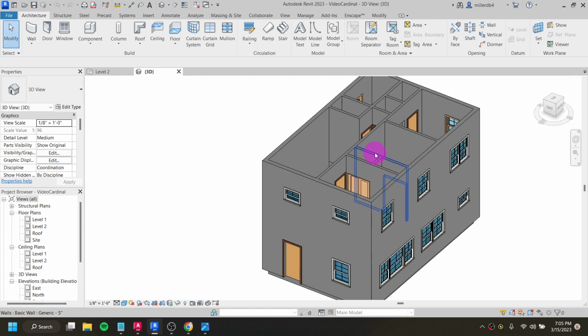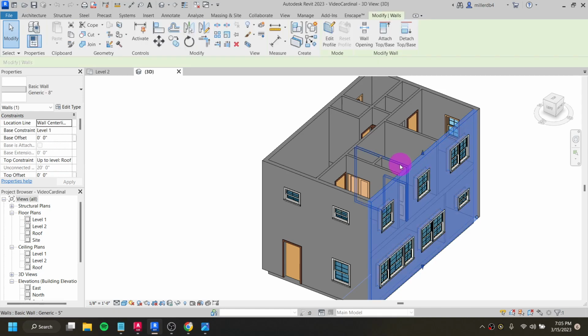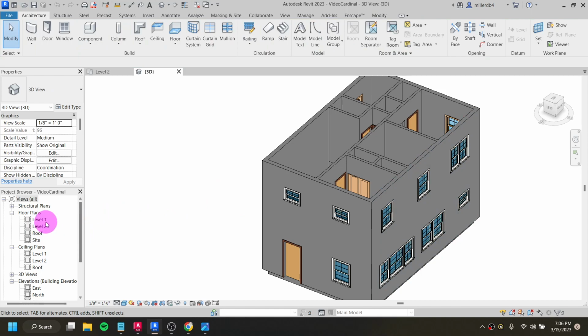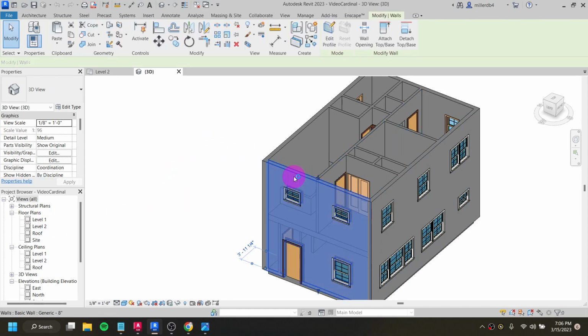However, I didn't want that to be our first introduction to Revit because it is a little bit of a cumbersome task and it may seem more complicated than it is. So what we're actually going to do is just edit what we already have as our generic 8-inch wall and edit our 5-inch wall. And by just editing these walls alone, we can then use them. If I edit this 8-inch wall, it's going to update any other one that shares that same wall type or that same family.